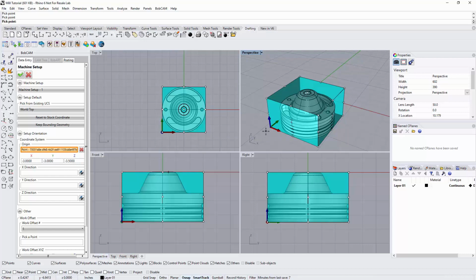Some routers, you may not have to do this, but some routers, you might be going off the spoil board. So you have to remember that the top of feature would now be 3.5 inches tall. And so when we start toolpathing, we need to make sure that our origin is referenced properly. Basically, what we're choosing right now is the location that is shared between this selection that we're picking now and the selection that we're going to have at the machine.